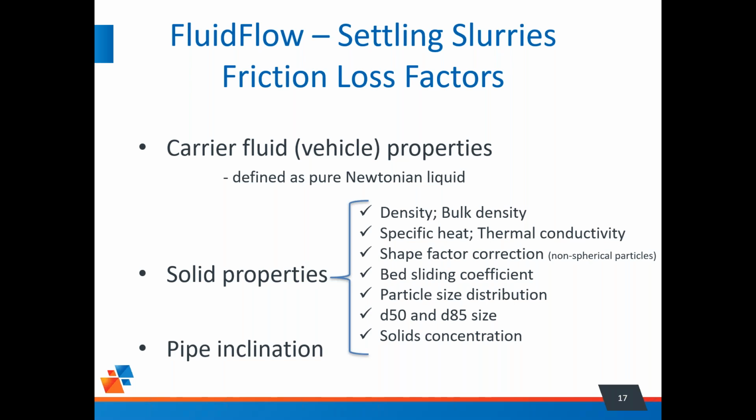There are different shape factor definitions in literature, but FluidFlow uses the Clift shape factor. As you'll see later on, there's a setting in the options that we can turn on. It's off by default, in fact, to allow for this kind of shape factor. Some other important properties of the solid, defined in the solid database: bed sliding coefficient, and we'll talk about that in a bit more detail later on.